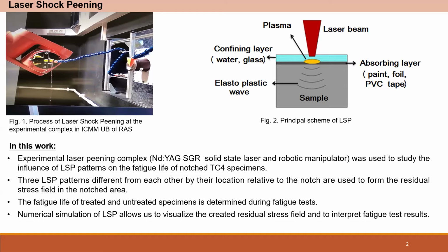As I said, this method can improve fatigue life and corrosion resistance, and if compared with other surface treatment techniques, the advantage is that we can treat and improve surfaces for geometries with very difficult structures, and the depth of residual stress that we can form is higher.